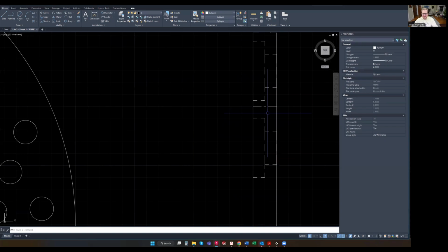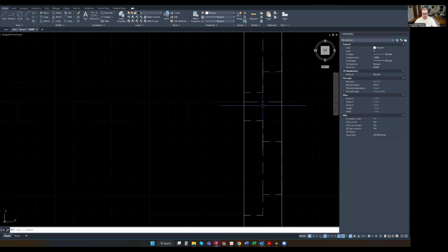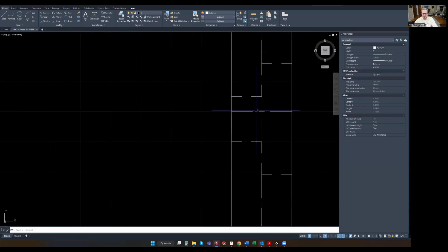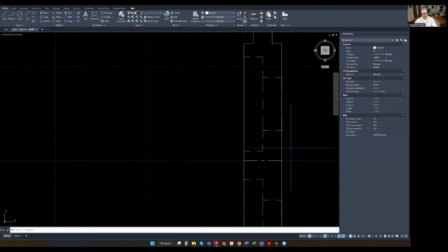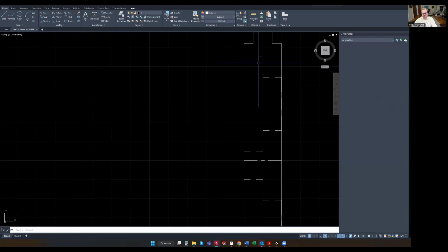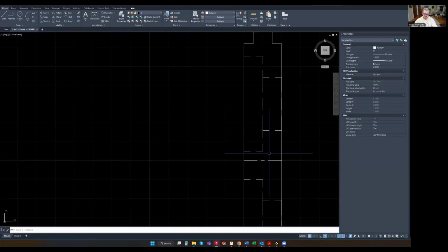And the reason we did that is because otherwise it looked continuous. And we want to denote that this is a center line. So universally speaking, in CAD standards and drafting standards, a center line is going to be a long dash, a short dash, long dash, short dash. Just like normal dash lines like this are almost always used, in product design at least, solely for hidden lines.